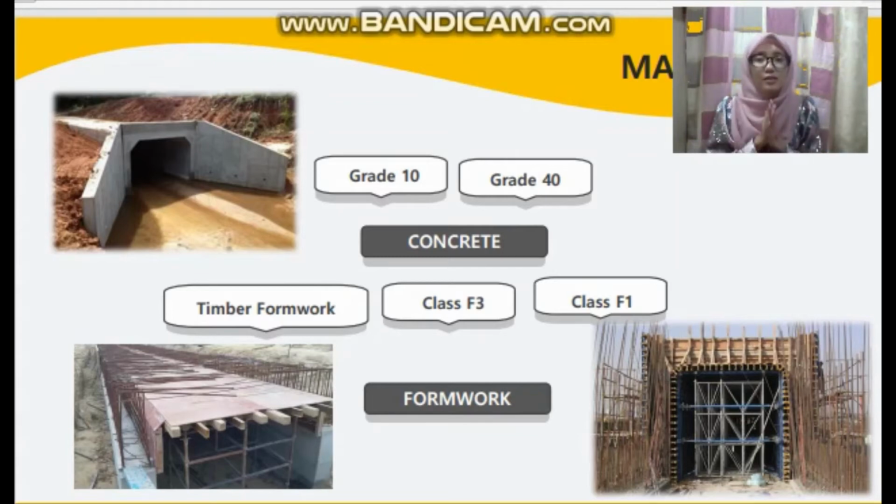Traditional timber formwork is made of timber and plywood on site. For larger structures it is simple to produce, but time consuming, and the plywood face has a relatively short lifespan. It is also commonly used where the cost of labor is lower than the cost of reusable formwork manufacturing.